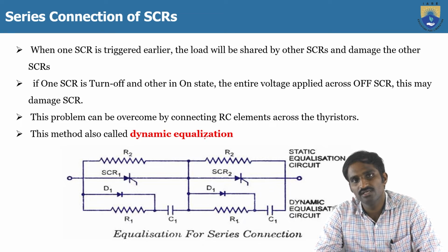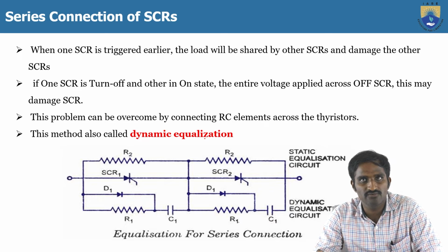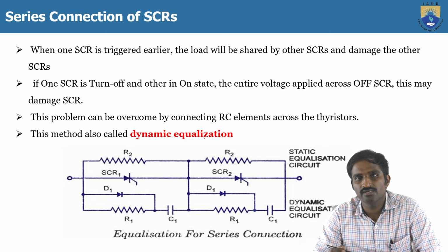And in the second case, suppose one SCR is turned off and the other is still in the on state because of the different reverse recovery time. Then again, the entire voltage across the string will apply across the one thyristor. Then the thyristor may get damaged.